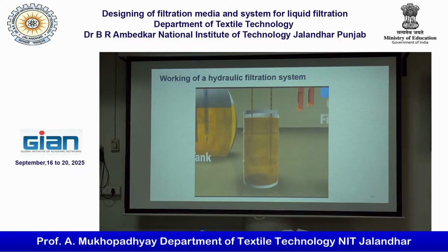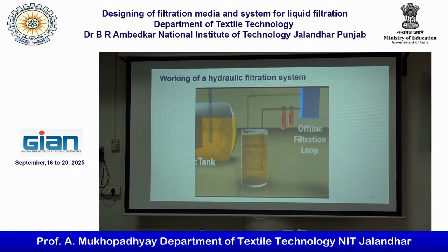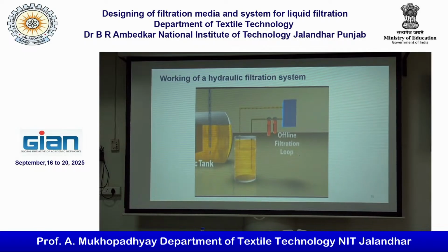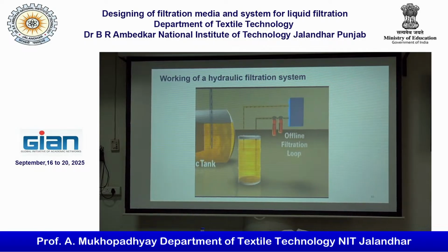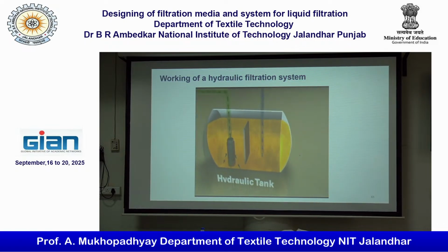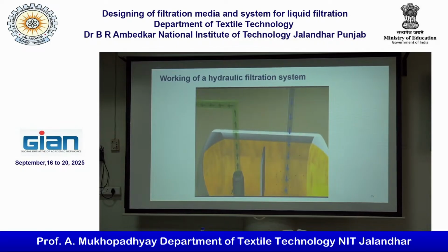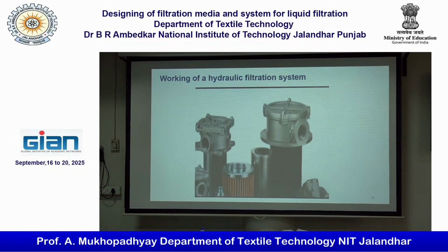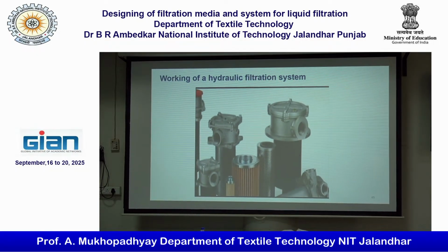This has prompted a leading global heavy equipment manufacturer to recommend filtering new oil before pouring it into the hydraulic tank. Water can also enter the hydraulic system via the holding tank when moist air inside the tank condenses as the outside air cools. So it is possible in offline mode also.